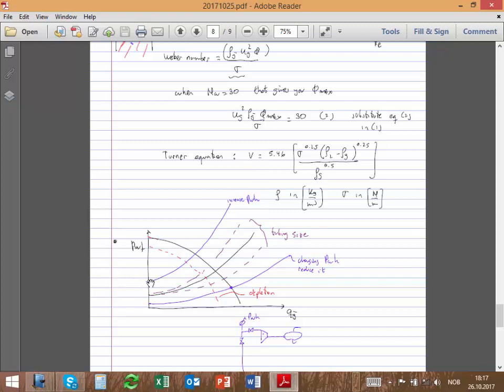Then, finally, the last thing in this class was, okay, what happens when we change wellhead pressure? Actually shifting the curve. Okay, changing the diameter is scaling the curve. Changing wellhead pressure is shifting it up and down. And I told you there are some ways we're going to talk about a bit more later, I hope, if we have time.